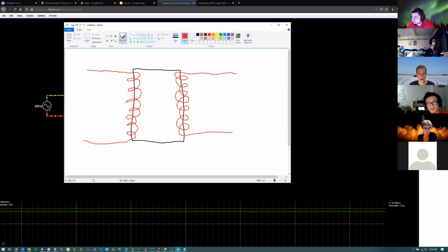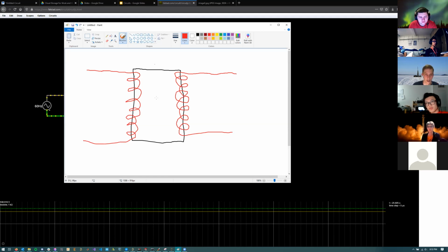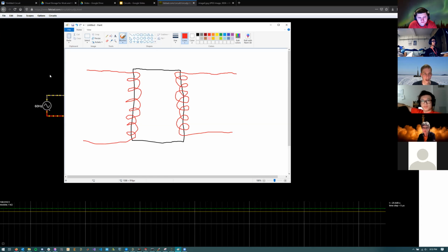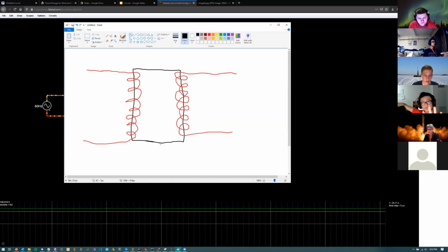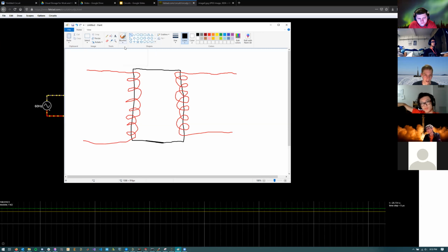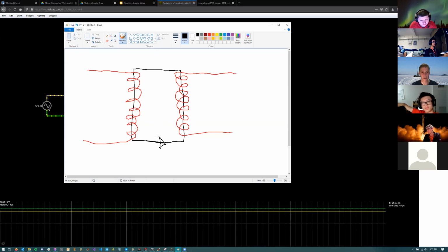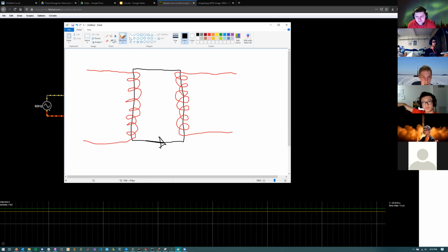So when you have current flowing through this inductor, like if you were to cover one side, it would just look like an inductor. You're going to create a magnetic field in this core, and so you'll basically have a flow of magnetism. It's the best way I can describe it, and it's very similar to electronic circuits. You can make magnetic circuits. A flow this way will induce a current in your wire winding on the other side of the transformer.